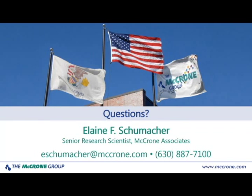That's a really excellent question, and you notice I didn't point out boron in any of the spectra that I showed, and that's because being such a light element, it is difficult to detect by EDS. The X-rays are so low energy that they have trouble escaping from the sample and making it to the detector even in very thin samples. The detectors are getting better and more sensitive all the time, so you stand a better chance of detecting boron, but it would be going out on a limb to say that you could really get good stoichiometry to look at boron in glass. You would have to go to something that is a better light element technique.